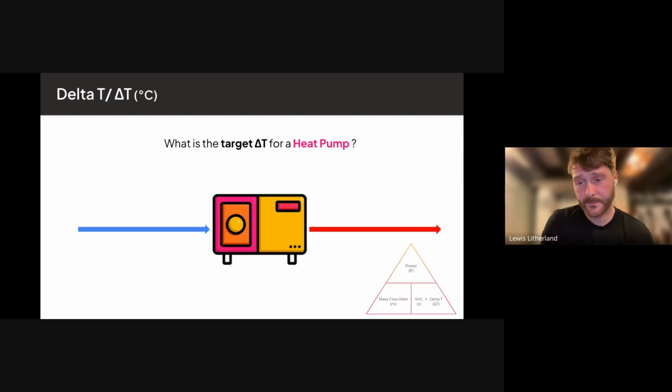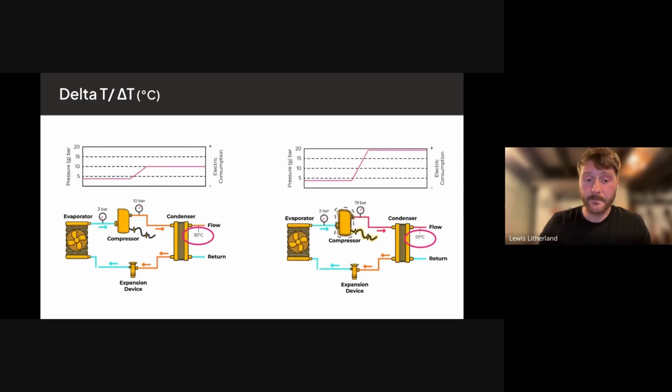So with the heat pump, the target delta T, I'll just move it on a little bit, is between 5 and 7. We're going to say 5 degrees for this. And again, as we emphasized before, it's a good thing for us because we can probably get that in most properties. You just have to be smart about where you connect your pipework in. When you're doing your primary pipework, if you go into the center of the property and split that load across, you can probably keep most of that pipework. Obviously do the calculations, which will teach you, but because it's so oversized, it's probably okay for this higher flow rate, because it was based on the non-condensing models.